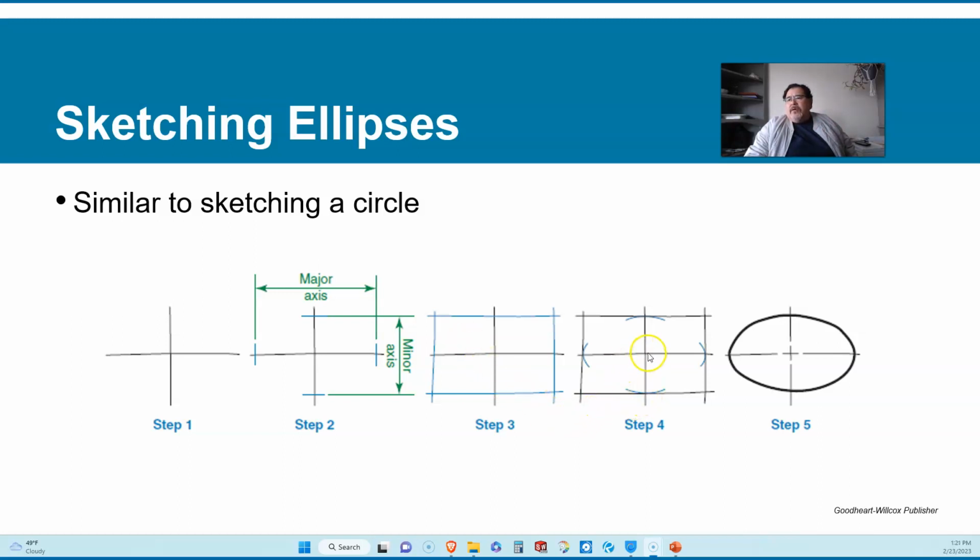And you can see, assuming this is the center, you kind of sketch the path of travel of the arcs from the radius, from the center where it crosses, knowing that they have to reach over to this one. So see how they aim for each other. So you just kind of trace within that area that you've sketched out to complete that ellipse.